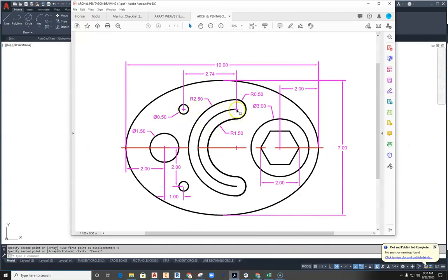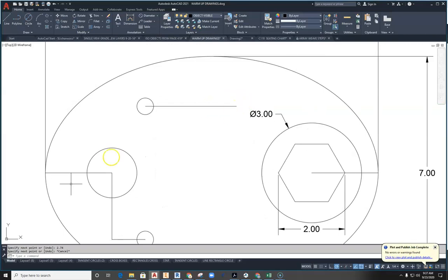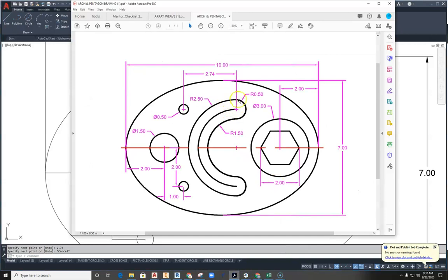With that set, I should now be able to continue. Now, the next thing, I'm getting spacing for these arcs. So if I were to draw a line at 2.74 from the center of the circle straight over, that's going to give me my start position for this arc. So let's go ahead and do that. Grab my line tool. I'll go center position over 2.74. And now I know the center or the start point for this arc. Knowing that start point is important, because then we can decipher the size of all of this information here. That center point is also the center point for this radius arc. So let's just work with a radius circle for now.